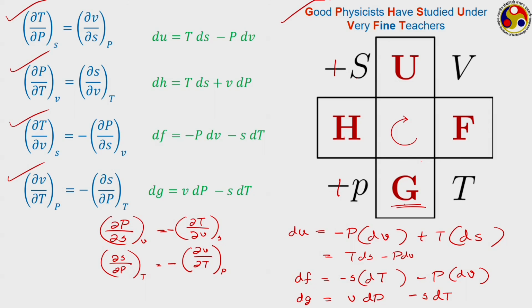But we started with the objective of developing relations of du, dh and ds. Of course, Gibbs equations are there, but like if you see here, the equation for du also incorporates ds. Similarly, dh incorporates ds. So, now we have to make use of this Maxwell's relation to update this Gibbs equation, so that we can replace this ds and write this only in terms of T, p and specific volume.